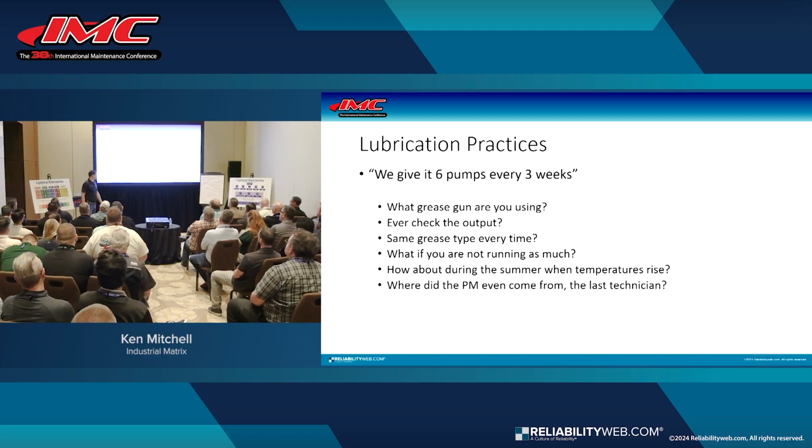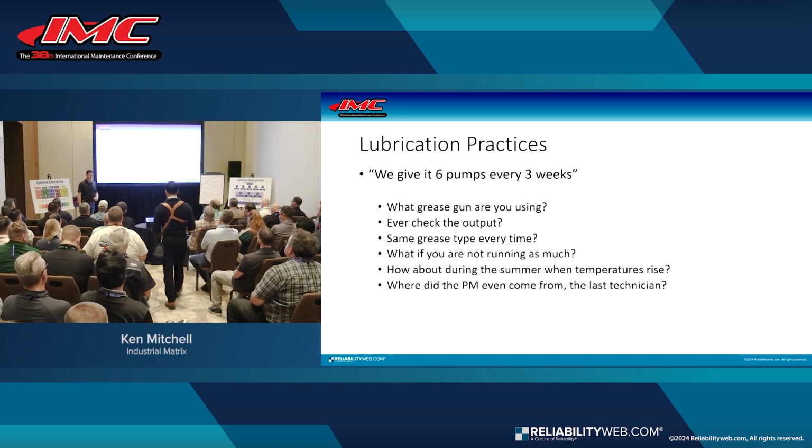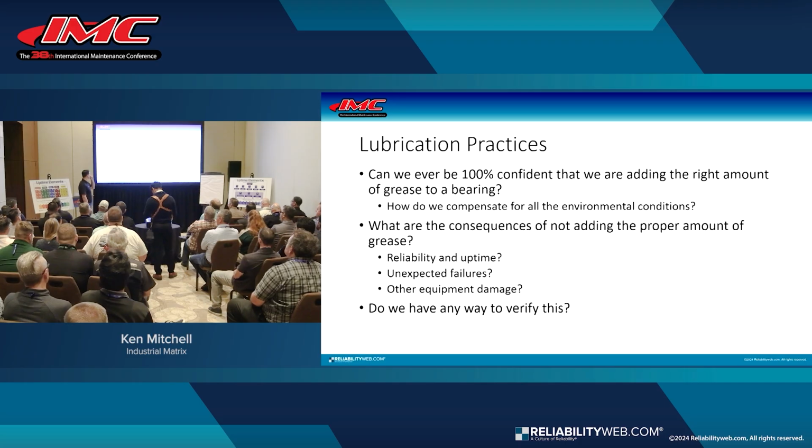And then I always like to ask, where did that PM come from? Whenever I'm inside of a facility, we're looking at grease PMs. How much grease are we putting in that bearing? Well, we do 6 pumps every couple of weeks. Why? It's what the work order says. So we really got to start by questioning what our grease practices are and how we can optimize those and move to the next level.